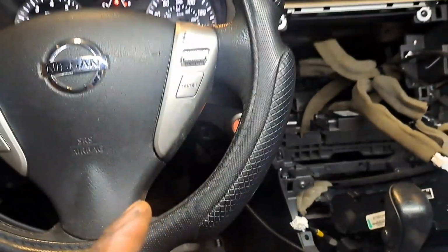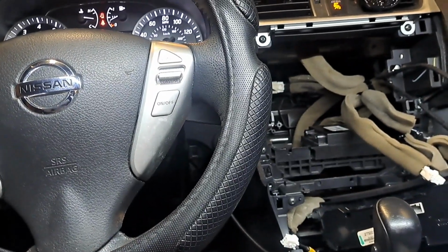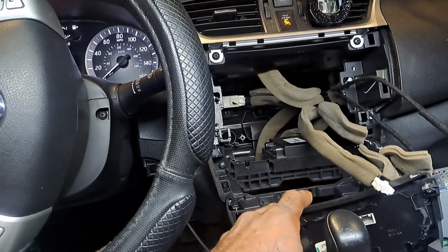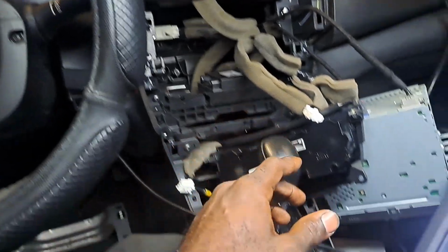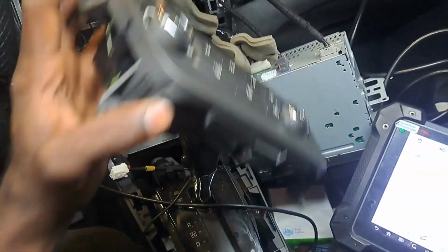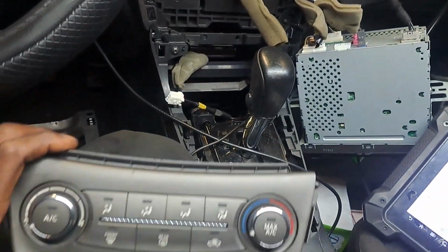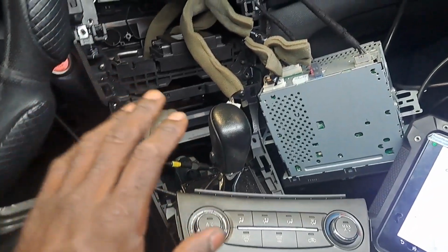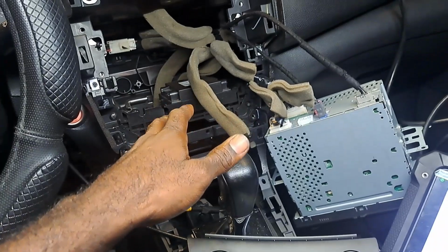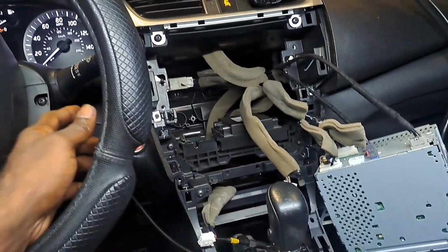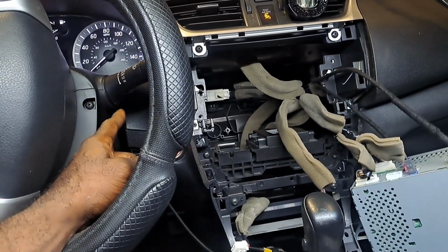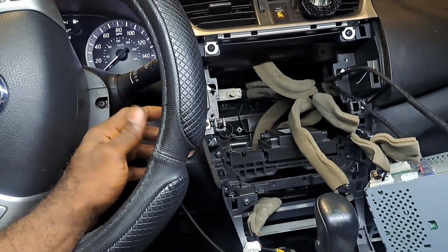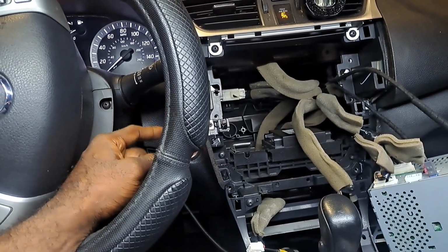Let me show you another key thing that I noticed. I have to let that deplete of energy and forget the state, because when I remove the control head here, it still wants to stay on. So just even from that, I can suspect the AC amplifier to be the problem, because if there was something wrong with the blower resistor, logically it may have stayed on, but that's not guaranteeing this conclusion here.